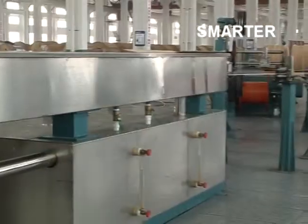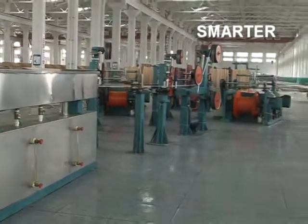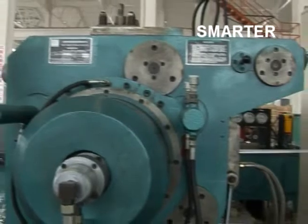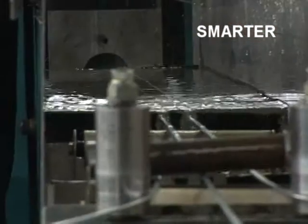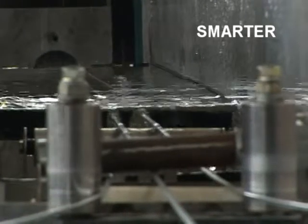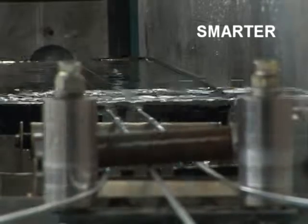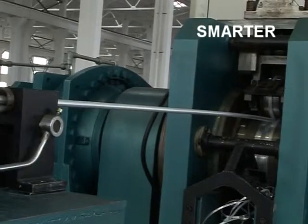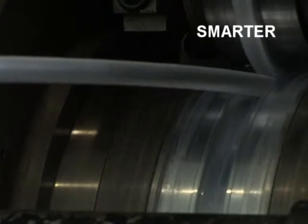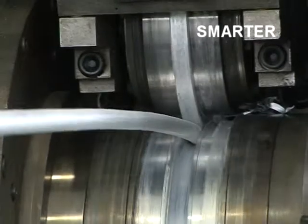Hydraulic, lubricating, and cooling system work for the extruder with a super high pressure to press the die holder. In the lubricating and cooling system, mediums are cooled by a heat exchanger without water circulation. The main shaft drives pressing wheel to rotate by friction. The die holder turns around the pivot with the help of two oil cylinders, leaning against the support of compact roller and being fixed by the compression cylinder.